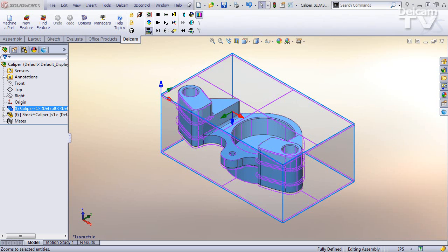Several improvements and enhancements have been added to the DFS interface for 2013 R2. Left and right mouse button clicks in the Delcam Manager behave just like they do in the SOLIDWORKS Feature Manager, providing more consistency throughout the software. You can show or hide features on a per setup basis. There are more color options. Plunge parameters are now split into their own category within Operation Attributes, and pop-up help items have been added to the Plunge parameters.